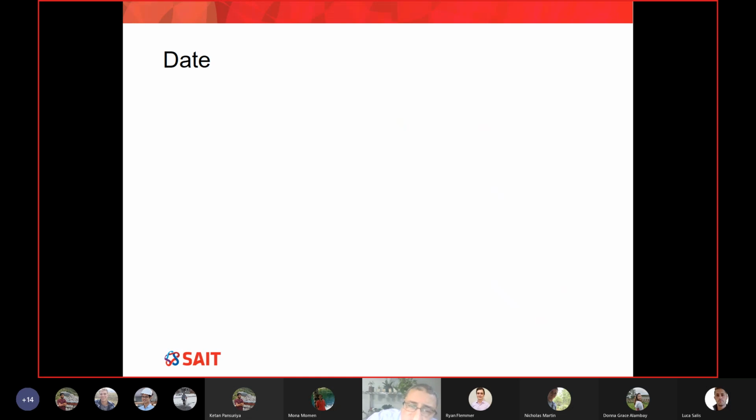Finally, the date. The date is very important, and probably some of you will question why. Why should I write the date on every single map? The reason is that reality is dynamic. Every day we're building things and demolishing things, which means the features on site that you survey in 2021, if you come back after 100 years, will simply be different.